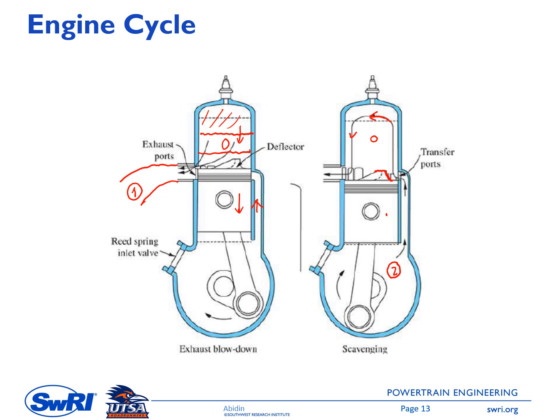center, it will move up again toward top center, and the crankcase volume increases and thus the pressure decreases. And you can see in here we have a reed spring valve. This is the inflow port of the mixture of air and EGR, or maybe plus fuel.